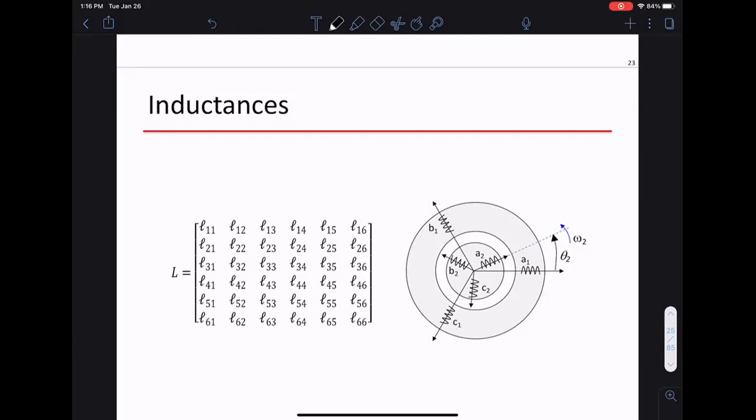So we have to analyze this matrix. At the end of the day, we have to analyze this matrix. What balanced three-phase does is create symmetry. For the same reason, we can work with balanced three-phase using a single phase equivalent. We said all the phases are the same. We don't care which phase we work on, just multiply things by 3. Same thing happens here.